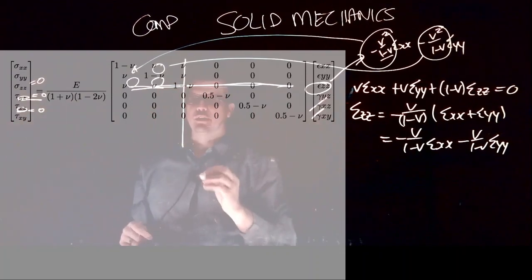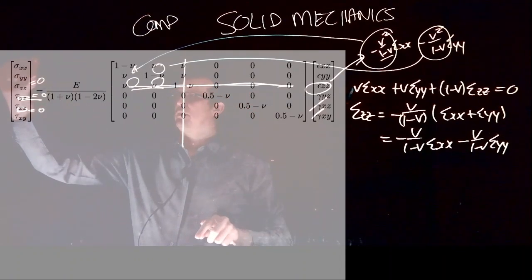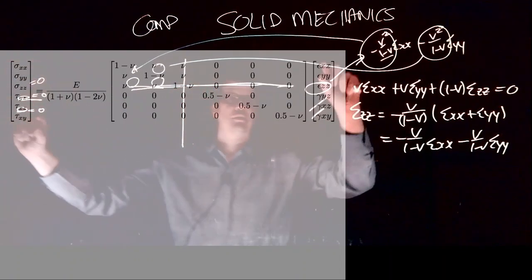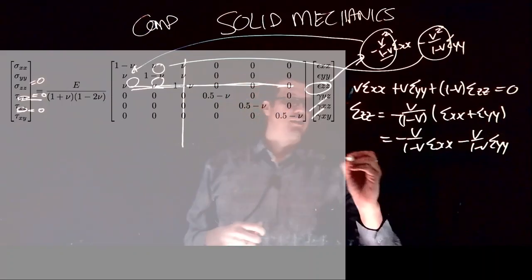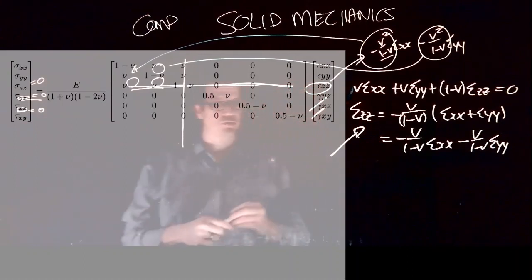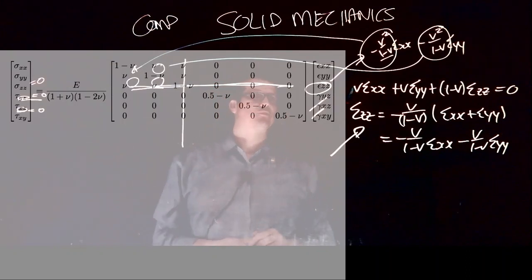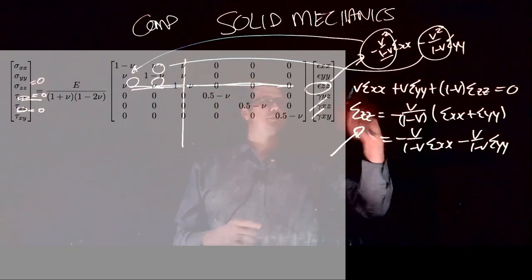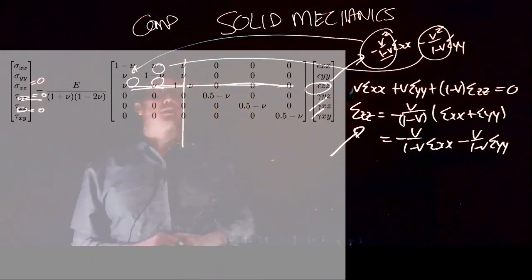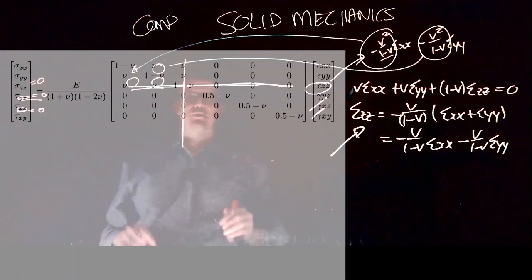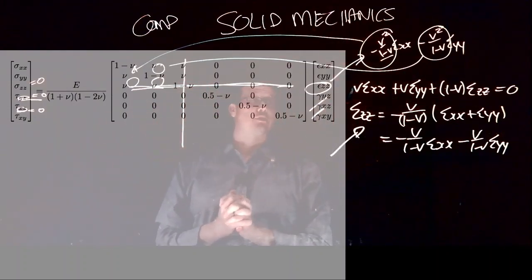That's why, when you look at the plane stress conditions, we solve a little 3x3 system. We solve for these stress components and these strain components. But don't forget, after the fact, we can then compute the out-of-plane response for epsilon zz. So this is just to give you a good overview of where the thing in the textbook comes from. I would like to say, please go do the derivation yourself. It's good practice to practice a little bit of SymPy if you want, just to simplify that expression and see for yourself that if you've done this, it gets you exactly to what you will see in the textbook for the plane stress condition.